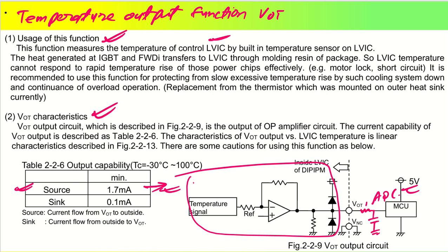So this is kind of my RC filter. This RC filter can have a value of, let's say, 100 ohm, and this can be, let's say, 0.01 microfarad. That is 10 nanofarad, you can keep, or even 1 nanofarad you can keep.